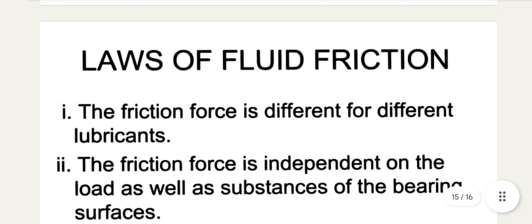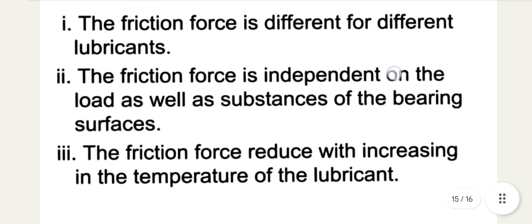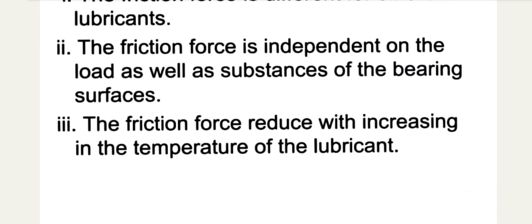The law of fluid friction: the friction force is different for different lubricants. The friction force is independent of the load as well as the substance of the bearing surface. The friction force reduces with an increase in the temperature of the lubricant.